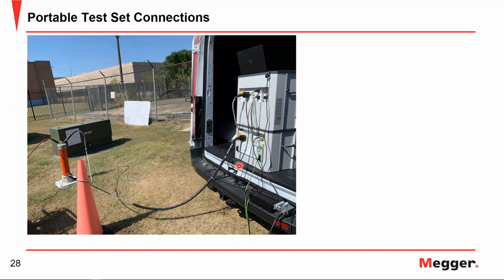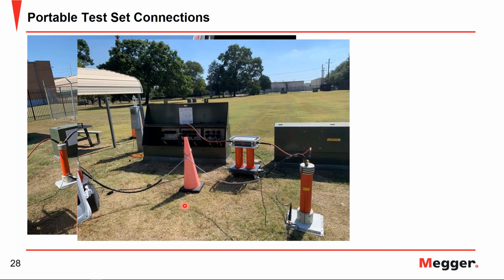So we have our high voltage cable, which again, I use my trusty traffic cone to keep air insulated and off the ground. In this case, you're going to notice what's called a support capacitor. This is just used in some instances. You may go out to test, and then when you try to perform your test, it says capacitance too low, can't charge the cable. In that case, you may need to add this support capacitor to add capacitance to the circuit.